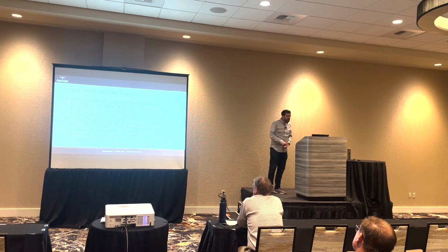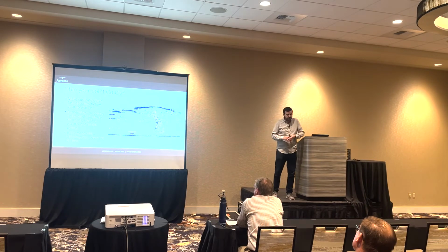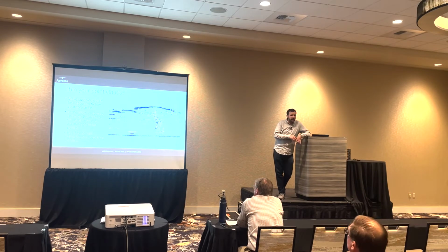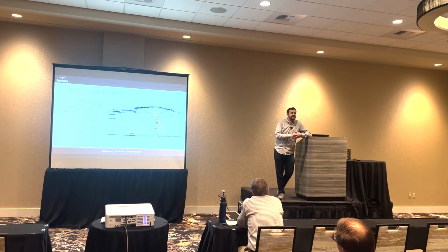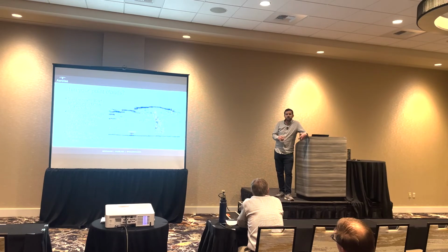All right, so the next step in creating your point clouds, and one of the big questions, is whether or not to thin your point clouds. I've talked about how there is such a thing as too much data. These LiDAR systems create staggering amounts of data. At least with the DJI L1, it can shoot as many as 480,000 LiDAR points per second. It's flying for quite a while too, and with multiple flights, it is not uncommon to have point clouds in the multiple billions of points, which is staggering.